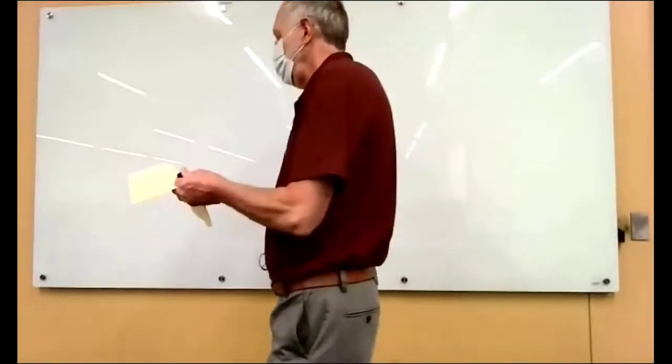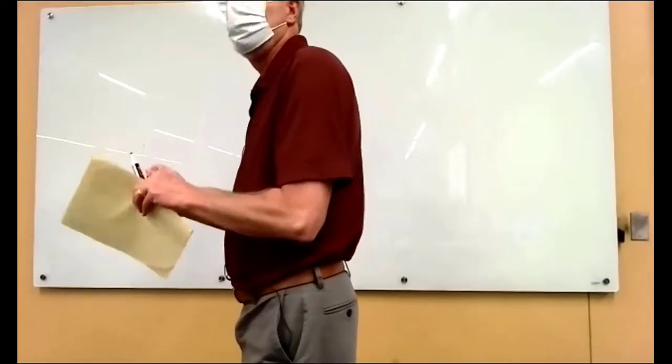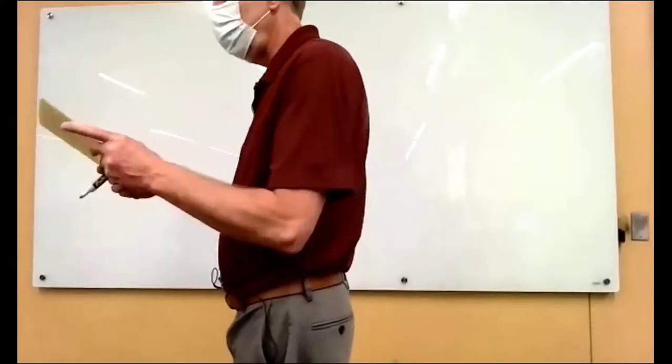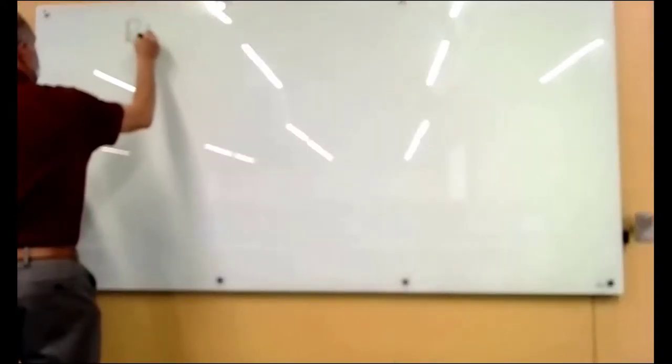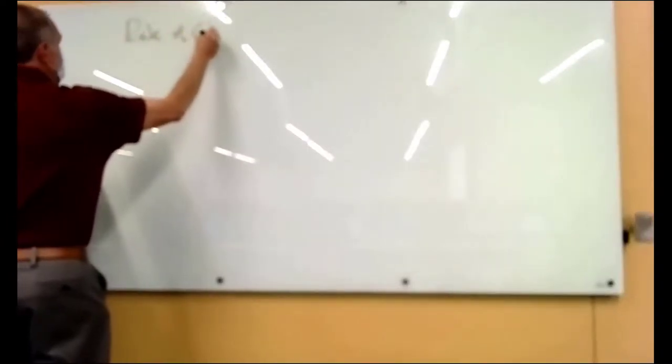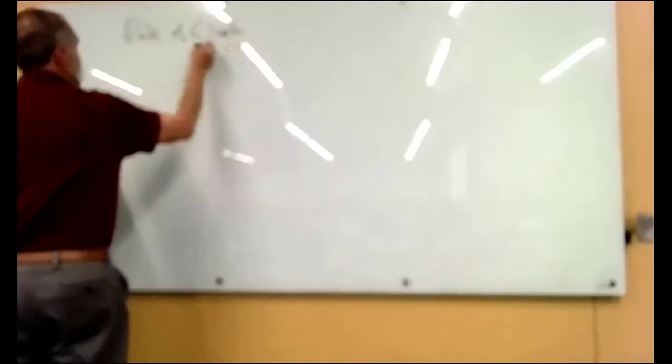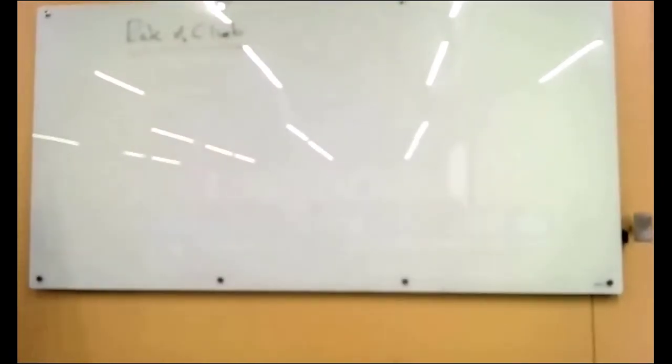And for climbing flight, we need to redraw our free body diagram and include climb. So our theta is going to be non-zero. So we're going to go back to our more generic version. Again, we're not gliding, so I'm going to do theta pitched up again.